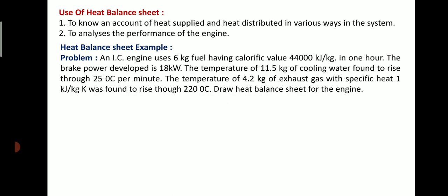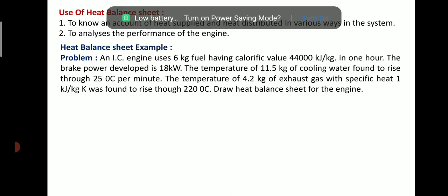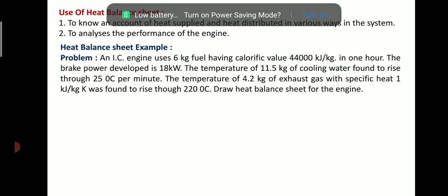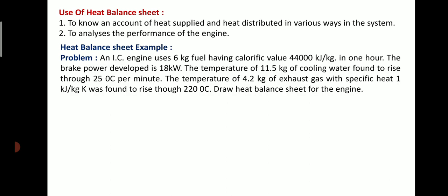The temperature of 11.5 kg of cooling water is found to rise through 25 degrees centigrade per minute. The temperature of 4.2 kg of exhaust gas with specific heat 1 kJ/kg K was found to rise through 220 degrees centigrade. What has been asked? Draw the heat balance sheet for the engine.